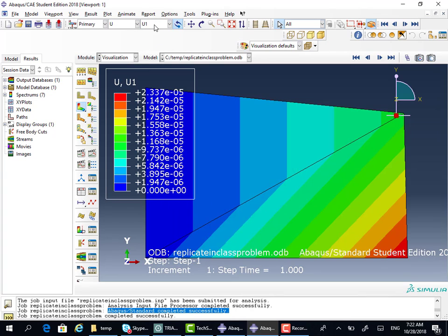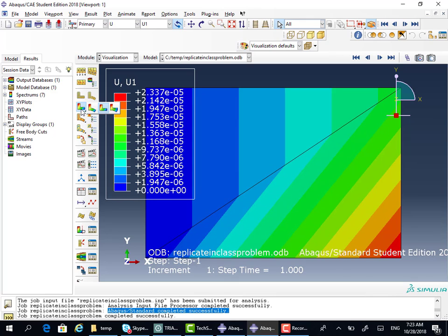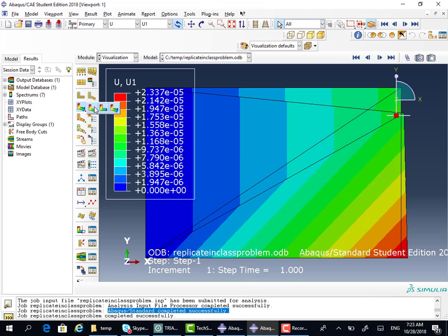So these are the displacements. So let's look at U1. So as we were expecting, the node here should displace more, and it goes down. And then this one, it's pinned, so it doesn't move. And then this displaces like this. This node cannot move in the y direction. It doesn't. And it actually would help if I put here the original versus the later, deformed section.